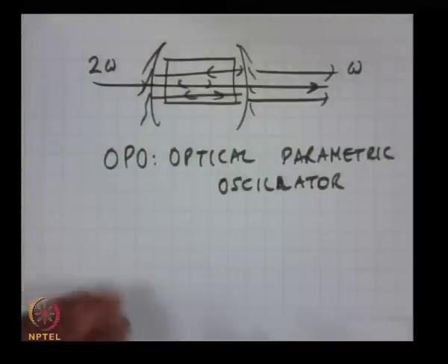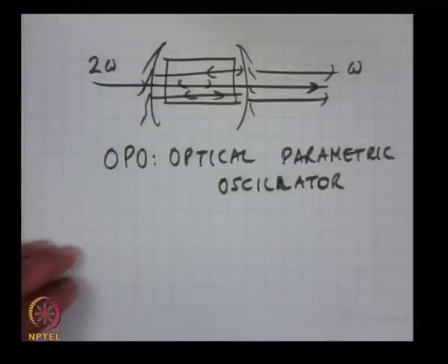So it can act like a noise-free amplifier, and that's very interesting for many applications where many times your signals are very weak, and if you want to amplify it without adding noise, that's very interesting. Any weak signal, if you try to amplify, that weak signal could be comparable to the noise levels, and you will be worse off by amplifying than without amplifying. So this is a very important property of this amplifier. Other than that, these amplifiers are very important for making an oscillator.